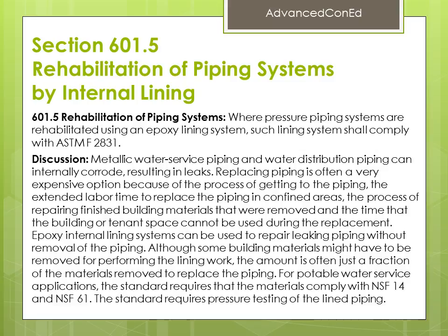Although some building materials might have to be removed for performing the lining work, the amount is often just a fraction of the materials removed to replace the piping. For potable water service applications, the standard requires that the materials comply with NSF 14 and NSF 61. The standard requires pressure testing of the lined piping.